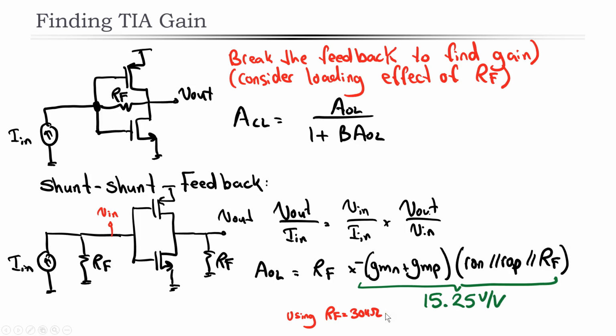Now, there's also one other thing it's important to point out here, which is that we are making an assumption that the RF resistor here is unilateral. But it's not entirely true, because there are two paths for the signal I in to reach V out. One is through the amplifier and one is through the forward path through the RF. In reality, that forward path here is being ignored, and its effect is really minor anyway. But generally speaking, this equation of feedback assumes a unilateral beta network. The feedback network is supposed to be only backwards. But that's not a problem. It doesn't really have that much of an effect here. But at the end of the day, we can see that in fact we can calculate the gain of this amplifier, the open loop, including the loading effect, in this fashion.